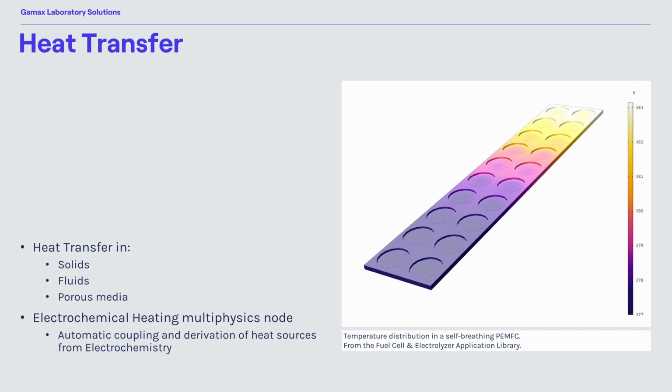And for the third and last model, we can extend with the fluid calculations. So that's the most complex geometry here and the most complex physics also. We have different compartments, different channels for the flow of the air and the H2. There are different sections for the anode and the cathode. We have the membrane, we have the cooling channel. So it's quite complex. Let's go into our model and investigate what different setups are made there and how it's looking inside COMSOL.